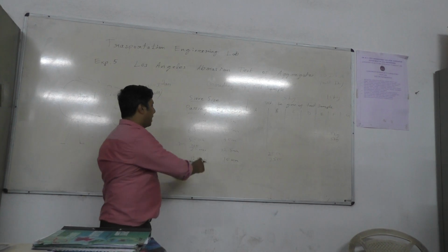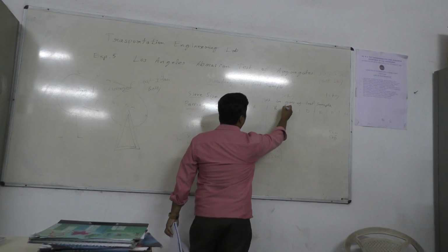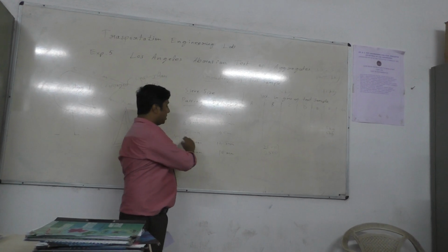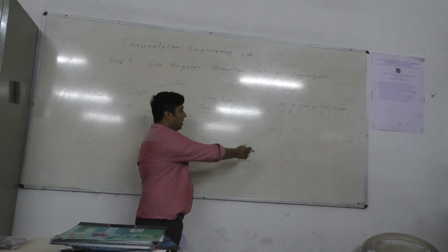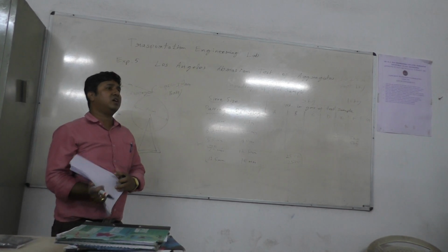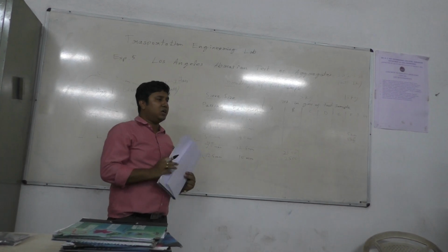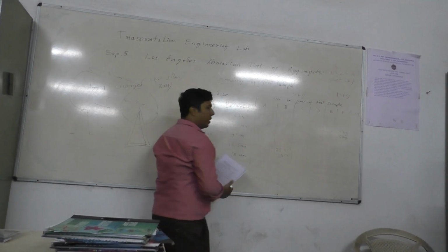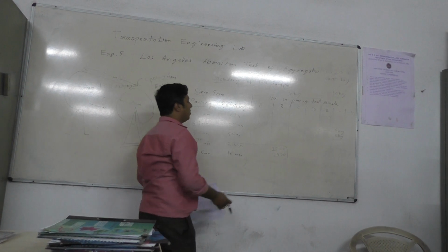Based on the sample that we have chosen, it will fall under category B, grade B. As per grade B, we have to take the sieve for passing 20 mm and retaining 12.5, and passing 12.5 and retaining 10, and we have to carry the sample 2.5 kg and 2.5 kg, and it will fall under grade B. There are different specifications for different grades of the aggregate. Based on this, we have to choose the number of abrasive charges. So for grade B, the number of abrasive charges is 11.